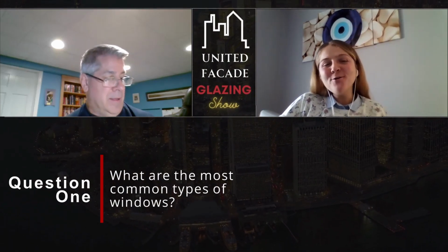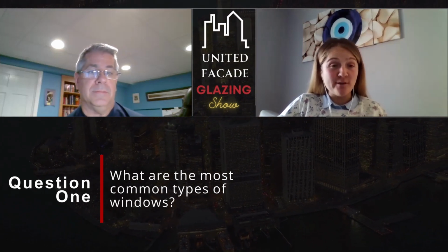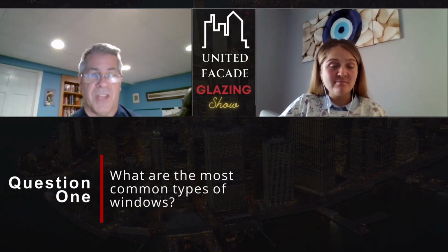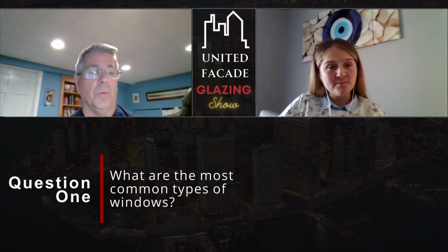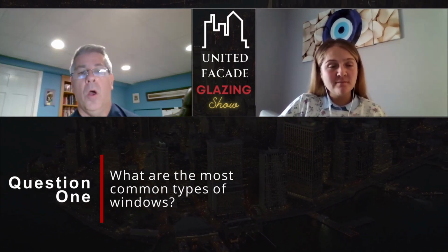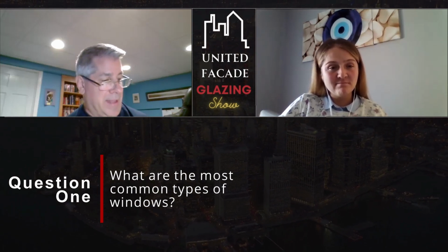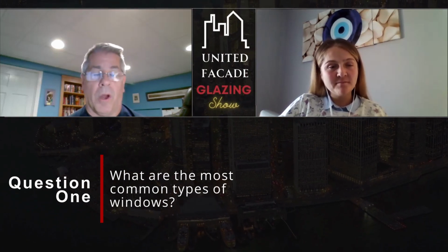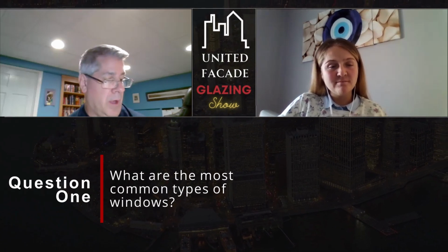Yeah. So what I learned from this is that a limit is a thing that is so important for the safety. Yeah, 100%. Yes, it's only there for safety, and it's regulated. And there are testing companies that will ensure that these parts and pieces that are added to a window are strong enough to withstand these loads. So it's something that's very important when an architect is designing a building as to figure out what he wants to do.